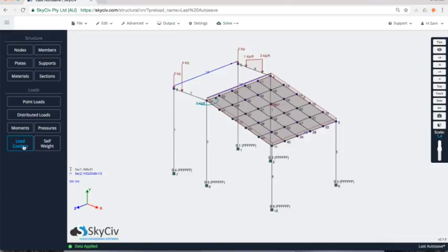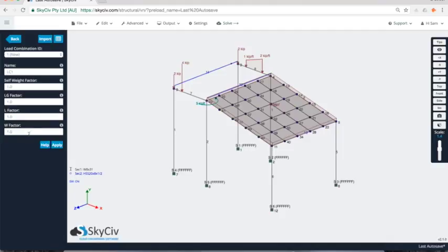Going back now, I want to maybe apply some load combinations to these different types of loads that we have. So we did have some dead loads, a live load, and a wind load here. Well, now we want to apply some load combinations to that. So I hit load combinations, and I have this in a format that I can control, add multiple combinations here.